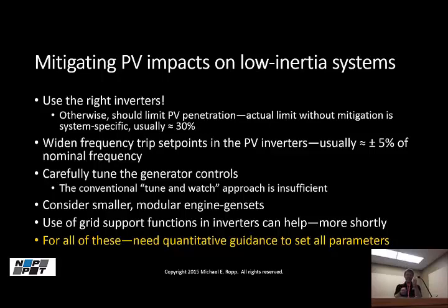There's two knobs on there, gain and reset. And those are the P and the I of the PI controller. So you basically just, according to a set of instructions, tune them until the thing looks about right. And I don't mean to mock that, because that's worked well for decades and decades.